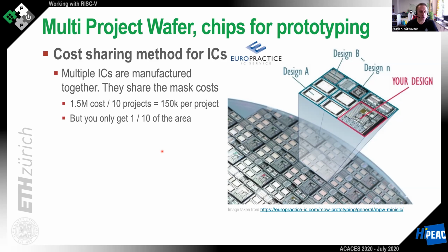So what do you do when you want to just test something? If you have an idea, you cannot afford to have a full production. So what is usually done is that many independent people join and share the cost of making the masks. This is called the MPW service.